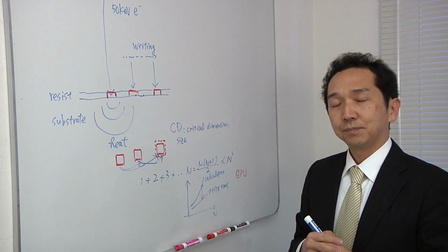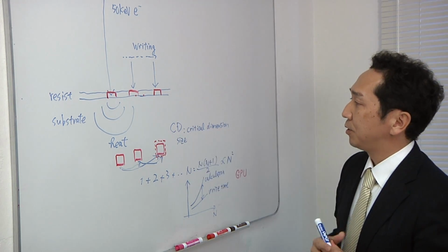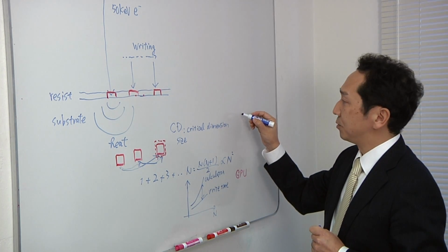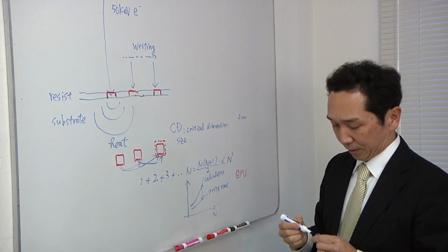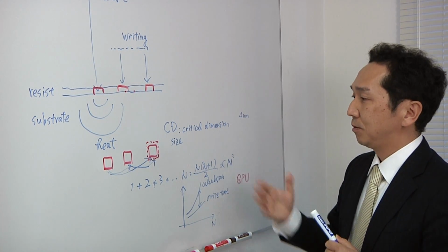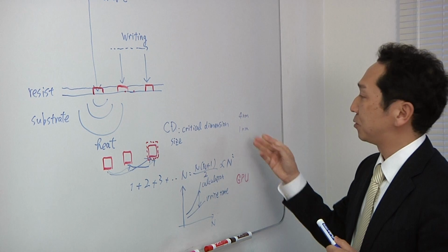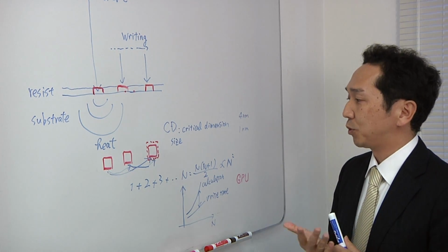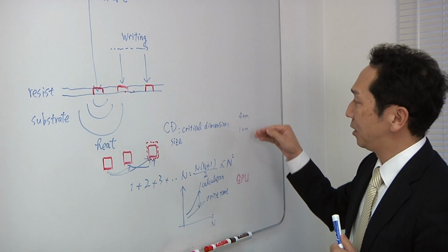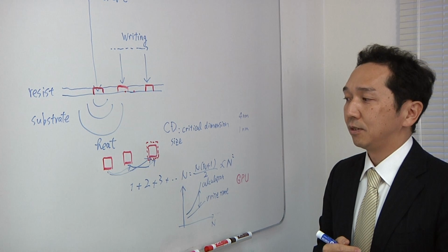Does this cause any mask warpage? Is that a problem because of thermal issues? Yes, the critical dimension error is increased to a maximum of 4 nanometers without any solution given. But we want some number close to 1 nanometer as a whole product accuracy, for the photomask product. So we have to do something to reduce the CD error to the required specification.